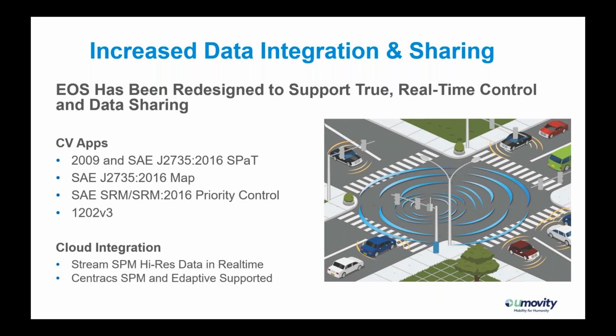So EOS has built on what we had with ASE3 connected vehicle, because we pushed ASE3 connected vehicle signal phase and timing SPaT to be one of the best in the industry, and now we have additional capabilities with EOS that make it even better. And that is the addition of the SAE J2735 messages, which you'll be able to get directly out of our Vissim SIL.